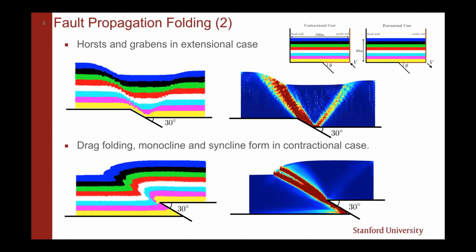And we're also looking at, for example, what controls the number of shear bands or faults in the weak material layers that we're simulating. What are the angles of these? And so far, we've seen that it's a combination, of course, of the material properties of the weak rock, the angle of friction, the cohesion, but also the angle of the basement blind fault is critical as well. For example, once it increases past 30 degrees in the extensional case, you stop forming these V-shaped conjugate pairs of shear bands, or what's called a graben in structural geology.